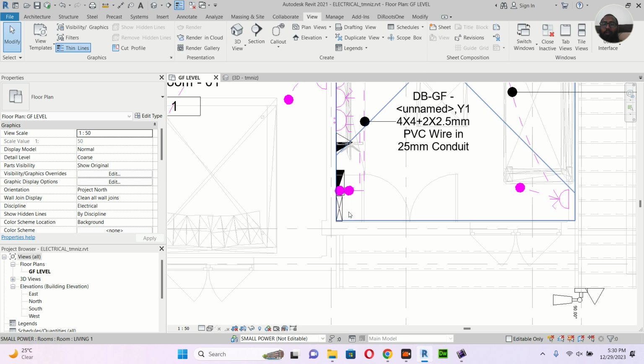Either you can provide a spare outlet. For the spare outlet, there are two types: switched fused spare outlet, and unswitched fused spare outlet. You can use either of them. With the fused unswitched spare outlet, nobody can switch it off or on. There's one small chip you have to remove. I will show you in Google. With a switched fused spare outlet, you can switch on and off. Normally the fire alarm control panel or IDF panel, we will normally use this kind of spare outlet.